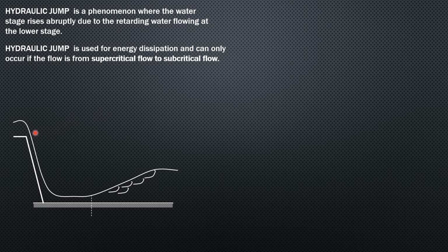So this is the situation. We have a spillway of a dam, for example, with water rushing down, and the velocity or the flow is obviously supercritical. Then it encounters an abrupt change in slope, from very steep to almost flat. This is almost flat; this is the apron of the dam. So the mass of water loses momentum. As a result, we have this hydraulic jump phenomenon.